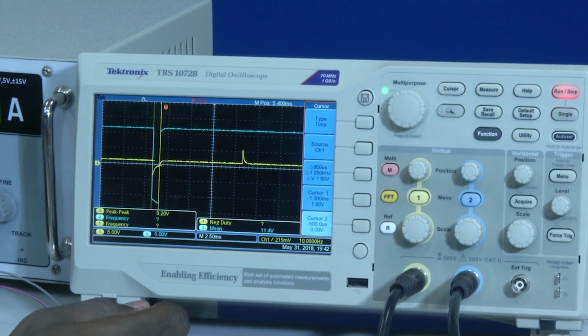So, when we provide a negative pulse, then the VA value is higher than the higher threshold value, making the op amp go to the minus VCC level, and then the capacitor starts discharging. Because of the discharging state, the output will be at minus VCC until the voltage across the capacitor is below the negative threshold value. When the capacitor voltage is below minus 7.5 volts, it goes back to the plus VCC state. So, till then it will always be at minus VCC.